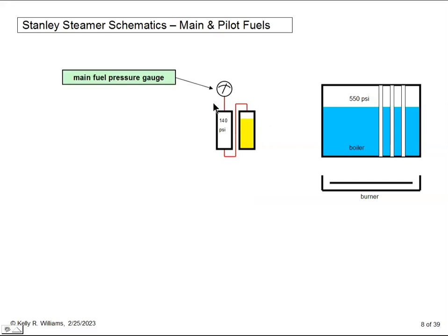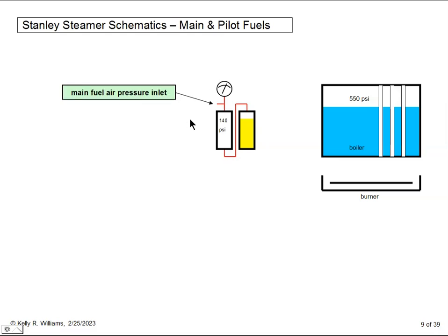So we add a pressure gauge, located where the operator can see it while driving. The air here in the pressure cushion tends to be slowly absorbed by the fuel, so it needs to be replenished sometimes. There's a connection here that looks like a tire valve and allows for adding air to the tanks.